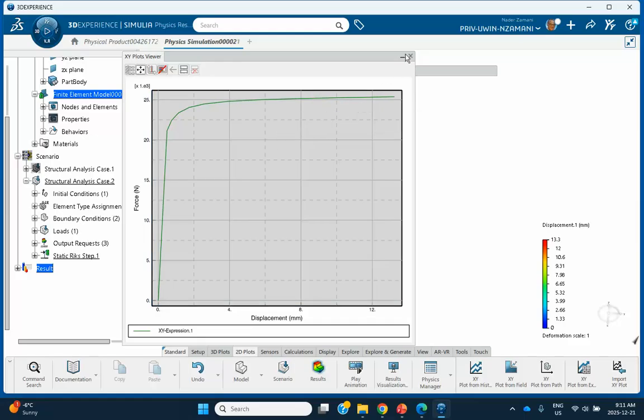Now, let me show you what happens if you change the imperfection. Now, I stopped after 10 millimeters. You can let this thing go on and on, and you get the post-buckling behavior. This is the post-buckling behavior, but you don't want to stop at 10 millimeters. You want to go up to a point where you get the full deflection load. In fact, if you did it, it will go like this. Let me use my cursor. It'll go up here, go to the right all the way, and then go up again. That's how post-buckling behavior for this beam will behave.